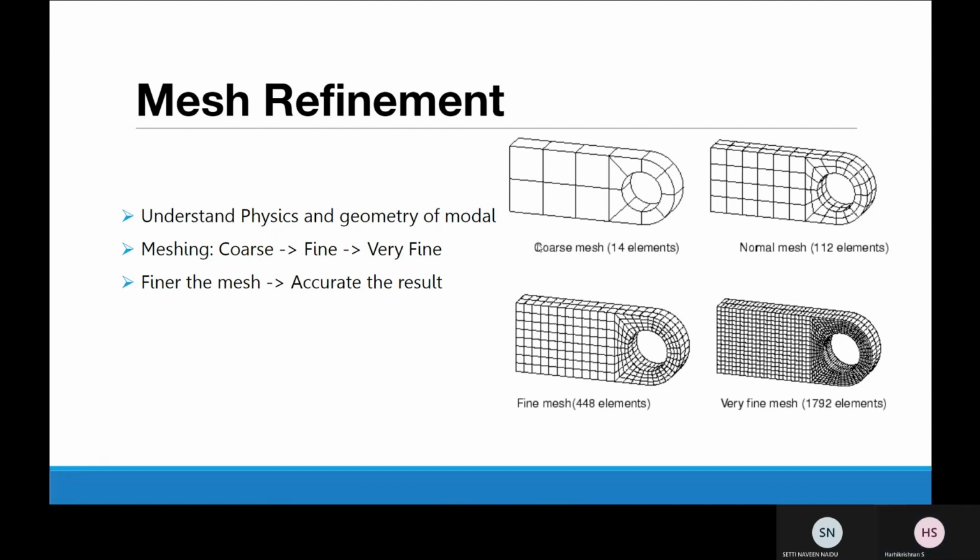So a coarser mesh is like a very large element. It looks something like this. A coarse mesh will require less computational resources to solve, and it may give a very inaccurate solution. It can still be used as a rough verification and as a check on applied loads and constraints. And do you know why I said this can be used for verification? Because whatever the mesh size, the trend is still going to be alike.